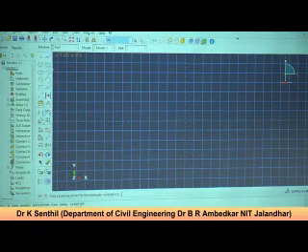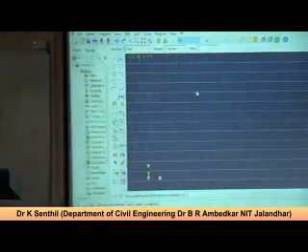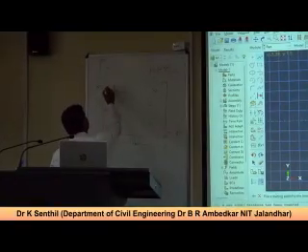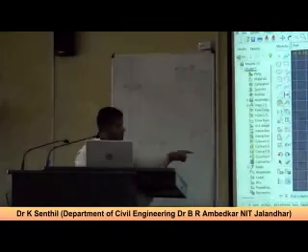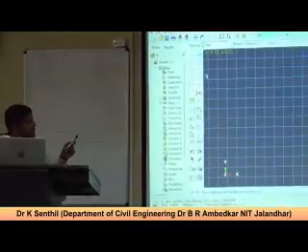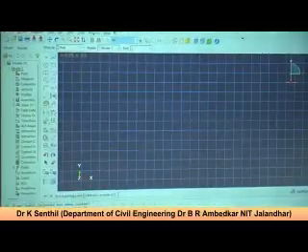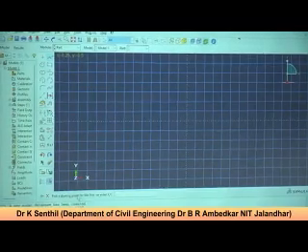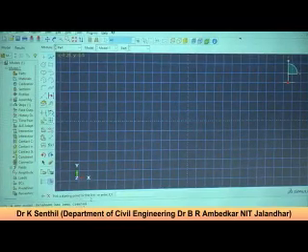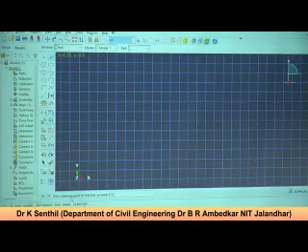Now let's talk about this one so that you will understand the coordinate systems. You start with maybe this will be 0, or you can take this as the origin. So this will be, you can say, 0 comma 0. When you actually click this, you have options, you read this. Throughout this analysis you have to read the command, what you have to do next, that will guide you. So: pick a start point for the line or enter xy data. Now I am entering xy data as 0 comma 0. We got it, right, 0 comma 0.